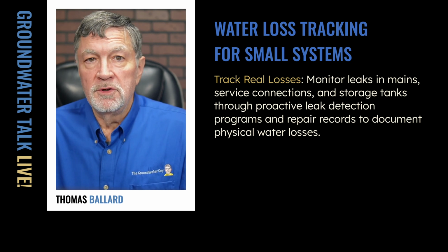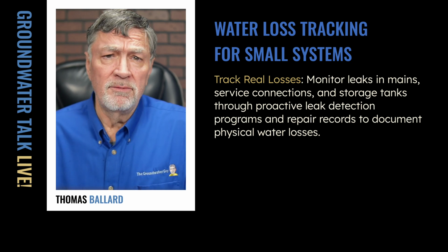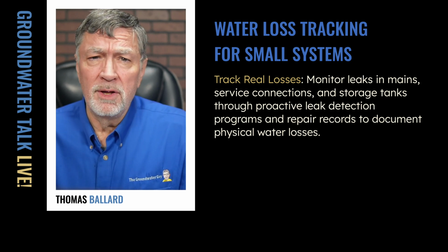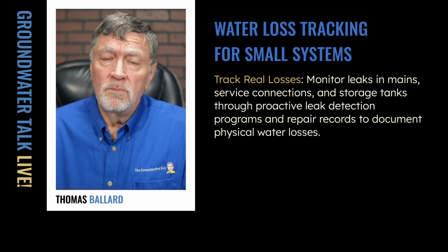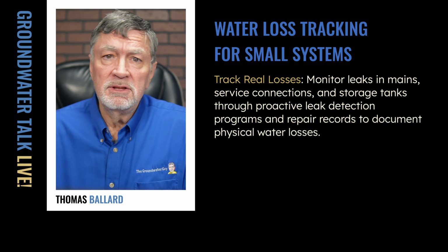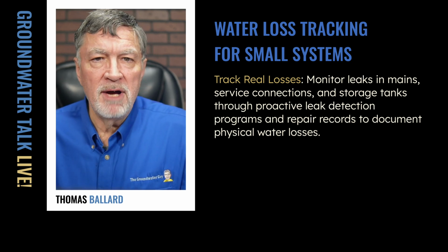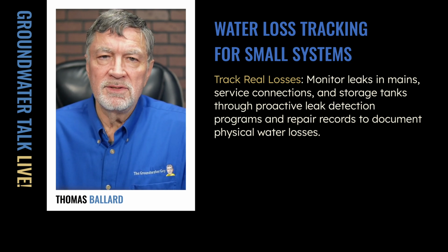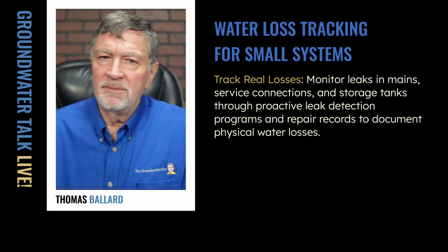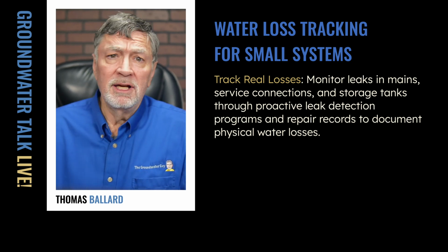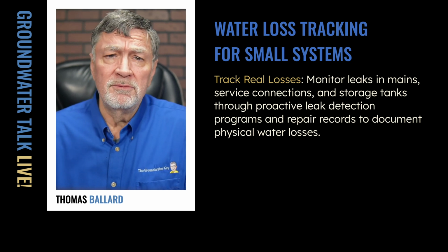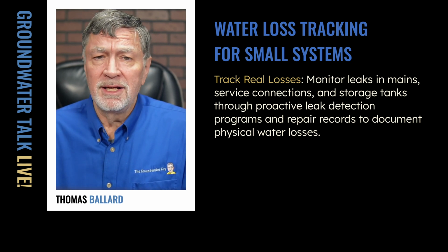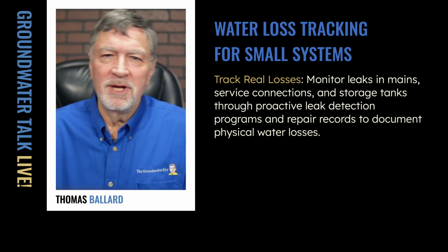So we'll in a future program talk about all the techniques that are available, but a lot of times water systems will actually even employ their own simple water testing or leak detection equipment. But you can contract with people to come out a few times a year, once a year, and test your lines and do the different tests. And just something as simple as smoke tests can really go a long way. They're relatively cheap to do, and tracking down those leaks is really going to tighten up the ship and allow you to get that non-revenue water back in the revenue category.